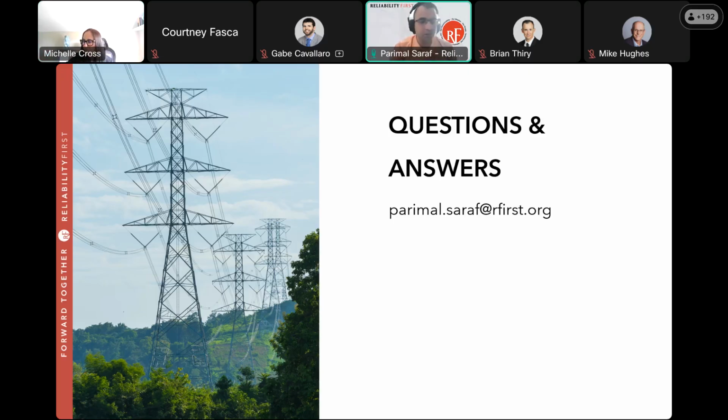So to the first question, whether there are any current installations of grid forming: regions like Hawaii, so HECO, which is their utility in Hawaii, require specifically grid forming inverters because, as I said, grid forming inverters have the capability to black start the system. They provide better system services in terms of how they support the system voltages and frequency. So in areas that are more islanded and not highly interconnected, grid forming inverters are more suitable.